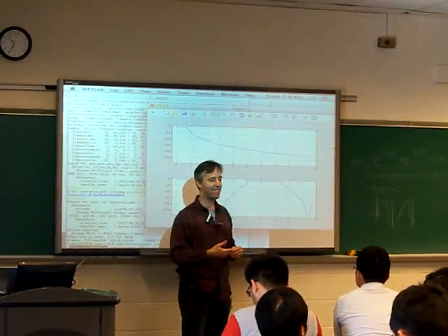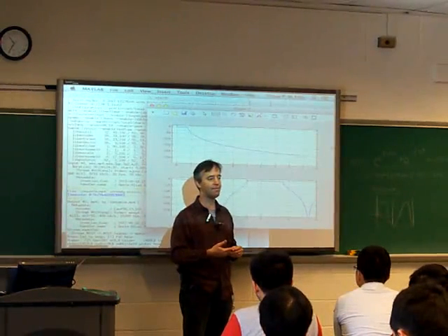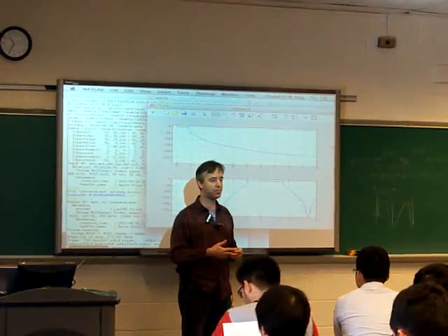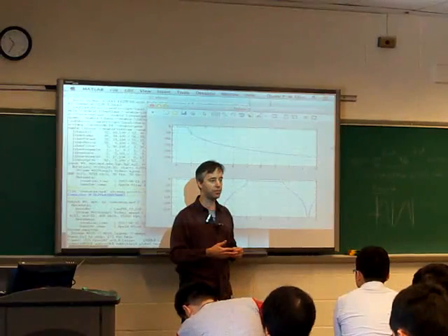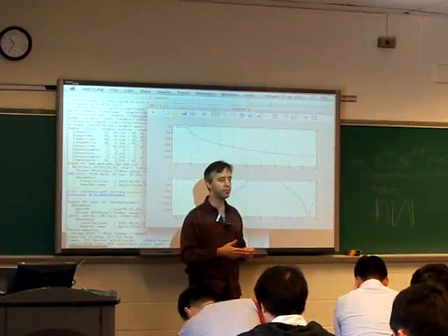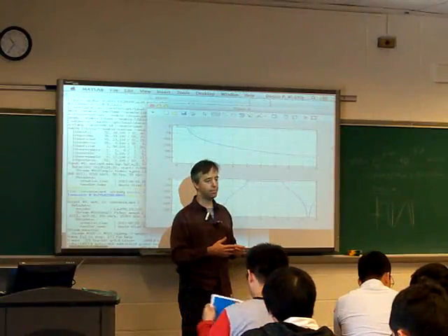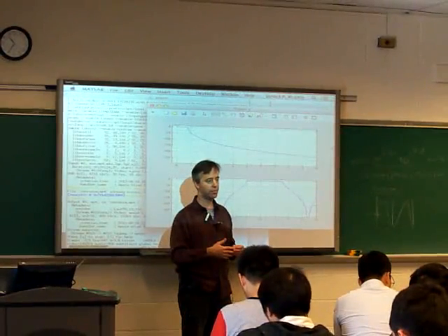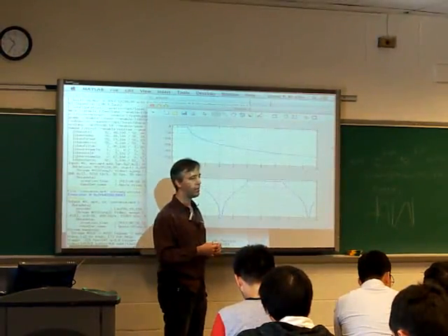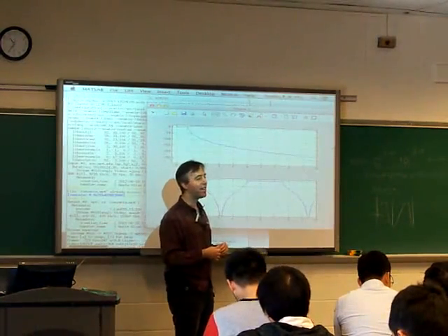So in the original signal, we're supposed to remove any high frequency components, like say from pi to 2pi, basically fs by 2 plus. But are we really concerned about high frequency components above 2pi, I mean above the sampling frequency fs? Because if we have a frequency component above the sampling rate, we cannot regenerate that in the digital domain. Right? We don't need to care about any frequency component higher than the sampling rate, like say all the images greater than